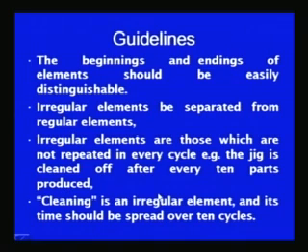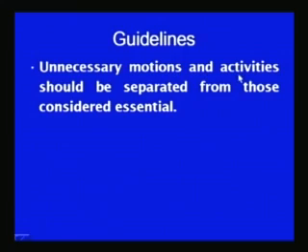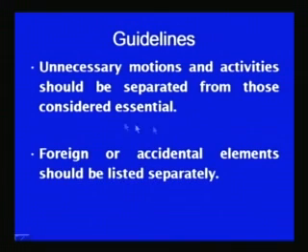That is why the study should be continued for a certain period of time, so that all those elements which are involved in the production process can be obtained and timed suitably. Another guideline in breaking the job into elements is that unnecessary motions are to be separated from those which are required for carrying out a particular job, so that unnecessary or redundant movements can be isolated, to reduce the time required for the job and to improve the method being used. Foreign elements and accidental elements should also be listed separately.